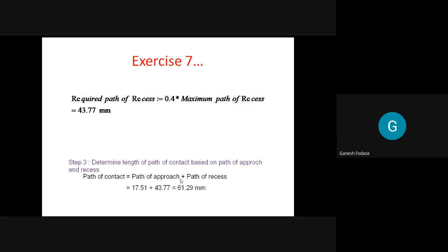Finally, we need to conclude whether interference occurs or not by comparing the actual value and the theoretical value. So numericals can be asked on whether there is interference or not, and we can check it by using different conditions that we studied.